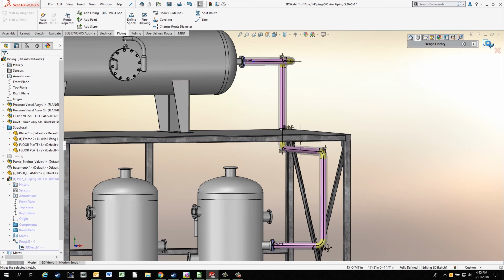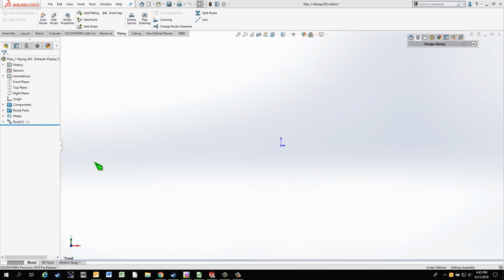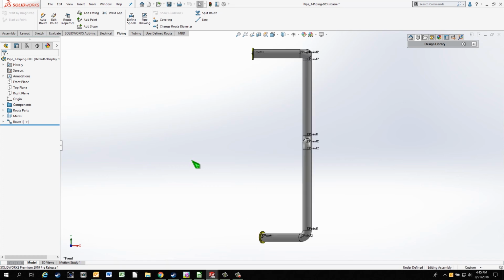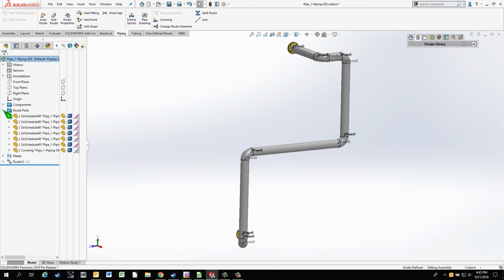The covering does intersect the hole in the riser clamp, but that could be cut and trimmed in the field, so it isn't anything for us to worry about. Covers typically are shown transparent in drawings, and in the assembly itself for that matter, so I'm going to open the route in its own window and make sure it's presentable for creating the drawing so that it does look transparent. That's all I'm doing here.